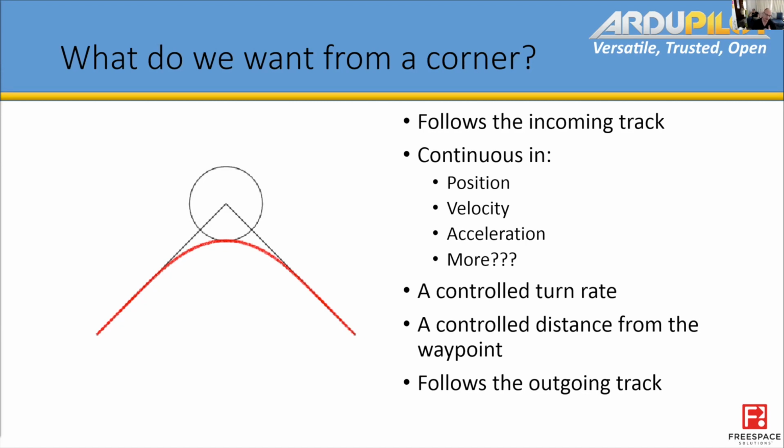So perhaps we can limit our corner speed to our maximum yaw rate, so that we can maintain a coordinated turn all the way through that corner. It needs to come in from a particular angle, go out on a specific angle, and then transition from whatever your maximum velocity is along those legs down to the maximum corner velocity you can maintain while obeying all your rules.